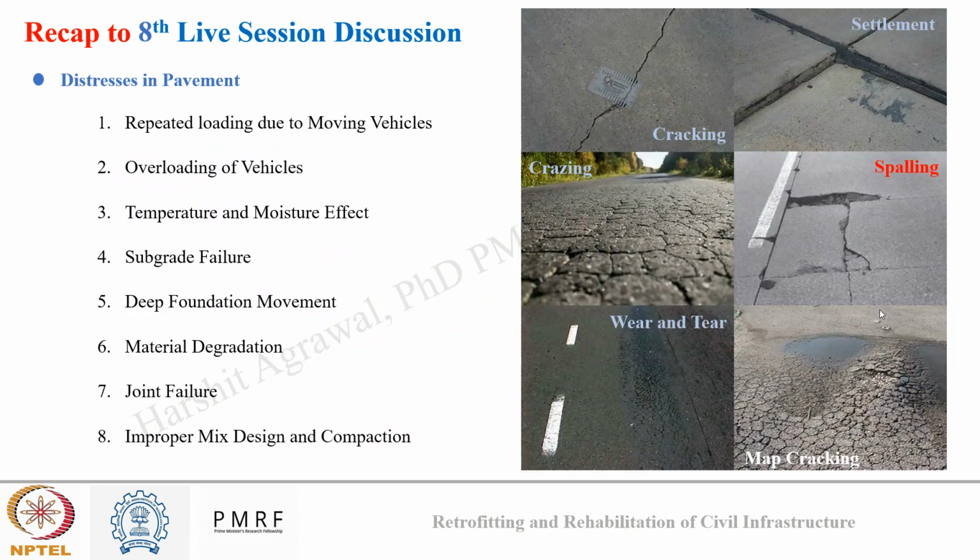Now, after the basic introduction, we looked into distresses in pavement. Here, we talked about different reasons for distresses. These were repetitive loading due to moving vehicles, overloading of vehicles, temperature and moisture effect, subgrade failure, deep foundation movement, material degradation, joint failure, and improper mix design and compaction. We also saw how we classify and identify these distresses in both bitumen and concrete pavements.